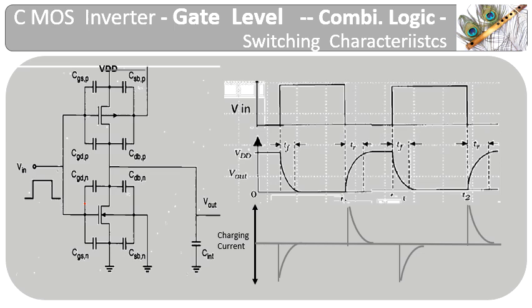MOSFET is a voltage-operated device, with forward transconductance gain, and is associated with several inter-electrode parasitic capacitances. The driven CMOS gate being a capacitive load, along with parasitics, gets charged and discharged, creating current transitions. The CMOS gate delays, in addition to input transition time and load capacitance, depend on several complex, nonlinear effects and phenomena.